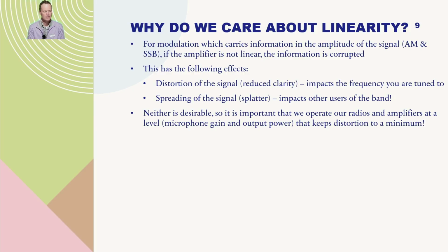But probably the bigger impact, or the one that can be an annoyance to our fellow operators, is spreading of the signal, or splatter. And that impacts other users of the band. Okay, so on VHF and above, it's probably a bit less of an issue in a sense because the bands aren't as crowded. On HF, I think it would be far more of an issue where the bands are a lot more crowded. So obviously, neither of those is desirable. We want to make sure the person we're talking to can hear us, but we also want to make sure we're not interfering with others when using our band or our spectrum, in a way that's considerate for other people.